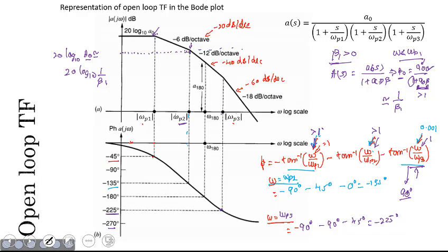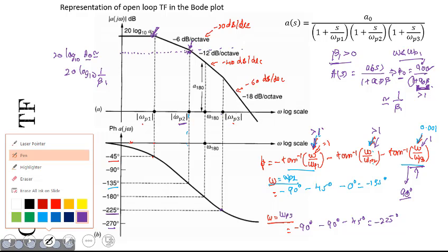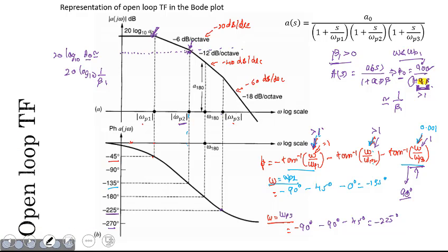So we have certainly lost some amount of A naught, or the open loop gain at this point is higher than the open loop gain that we had here, which means that at this particular frequency, I have a value of open loop transfer function gain that is smaller compared to the same gain that we had just before. True. Now, due to which, at that particular frequency, this term, A naught times beta, becomes almost comparable to the value of 1.